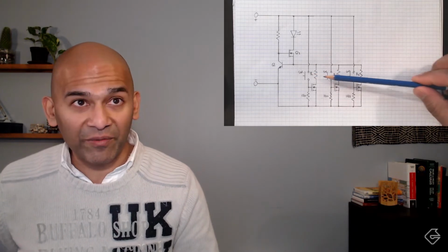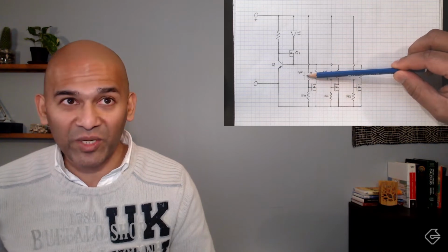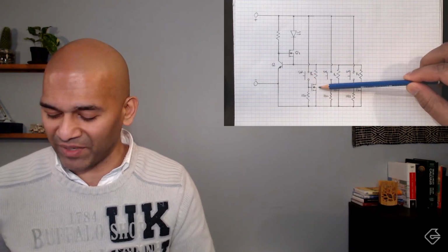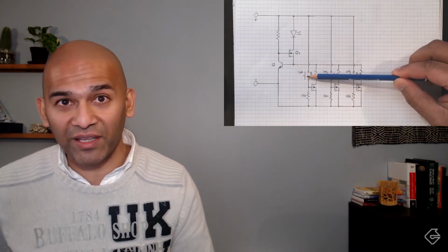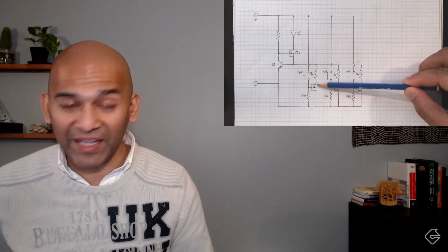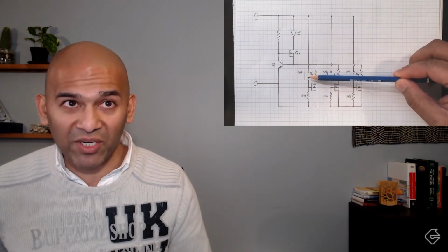We still have our 3 resistors, we still have our 3 switches, but there's a difference, of course. I've moved the switch up over here, and I've added those MOSFETs in the current path. So the switch isn't actually blocking the current. It's the MOSFET that's going to be blocking the current, and the switch is going to be turning it on